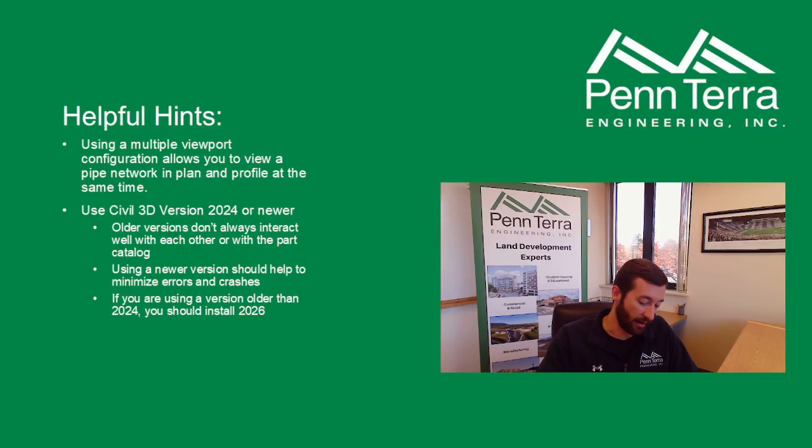Okay, now a few helpful hints as we get started. Anytime you're working with storm sewer pipe networks, I recommend making use of the multiple viewport configuration options within Civil 3D, because it'll let you view a plan and profile at the same time, or maybe you want to view a plan and your storm chart at the same time. Either way, it saves you a lot of panning back and forth and just makes things pretty quick.